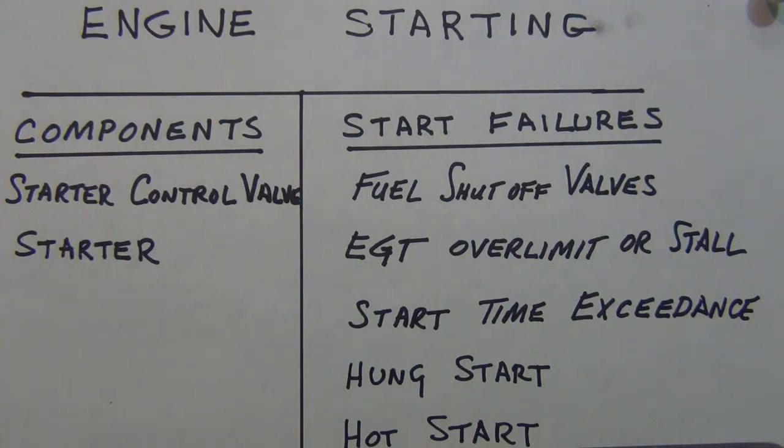Also, what you want to be aware of is you don't want to keep re-engaging the starter, because if you keep doing that, you'll ruin it, essentially. You do need to pay attention to that. Basically, you do not want to re-engage the starter above 20% of N2. If you do that, you're going to damage the starter or the accessory gearbox. So again, follow the manual as far as the process and the schedule of when you can do a restart and re-engage the start.